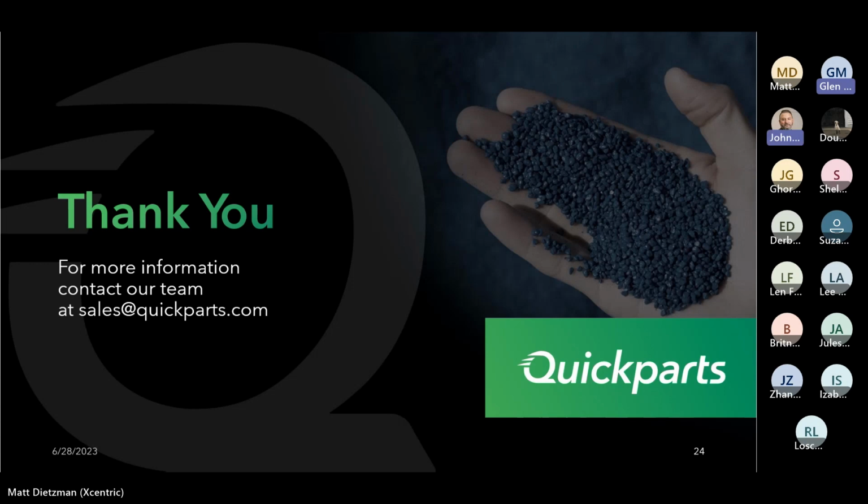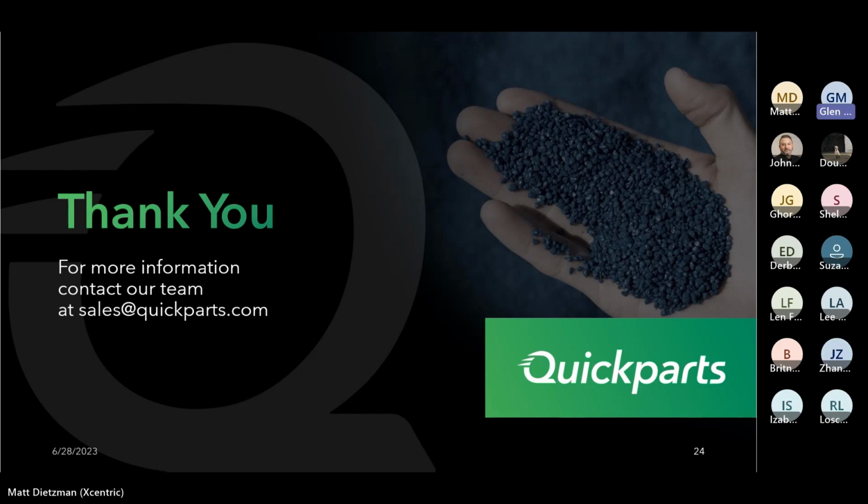Same with, Glenn, like TPUs, TPEs, TPVs, the more flexible, rubberier materials. You can stay within that family. A lot of times the customer will want us to run 4 or 5 different durometers, stiffness on the material, which in general will work as long as we're maintaining the same basic shrink rate and staying within that family of materials. Yes.